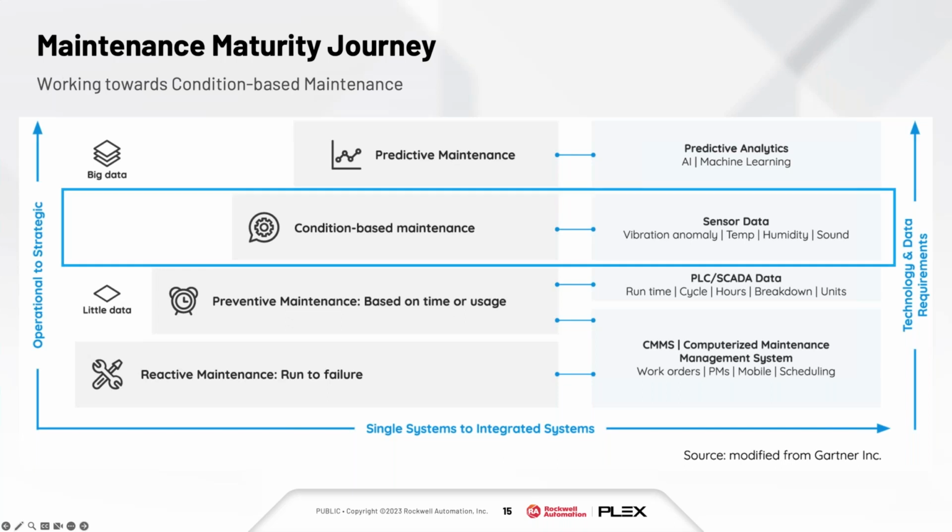And then we have condition-based maintenance, which is what we're really centered on talking about here today. Using the car example, imagine your car's engine had sensors and they could measure the viscosity of the oil and detect when it's too dirty. It could then alert you that it's time to change the oil to avoid any issues. You have the opportunity then to plan that maintenance based on the data coming off of the car and your driving schedule, to make sure you're changing the oil as it relates to your schedule and when it's absolutely necessary.